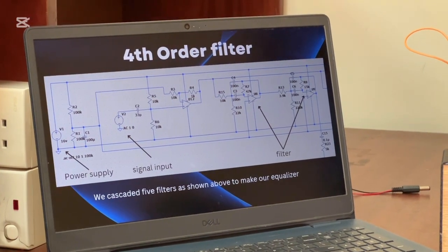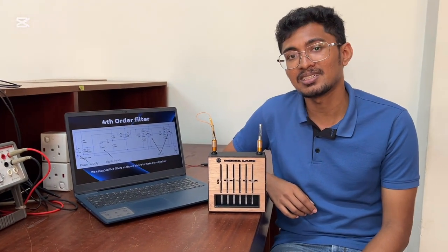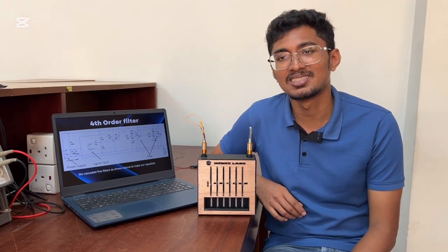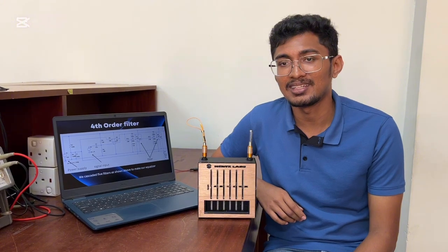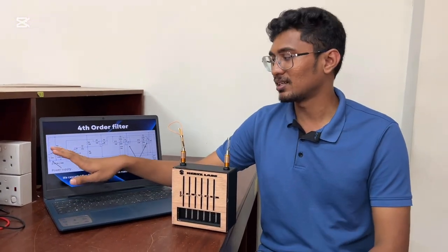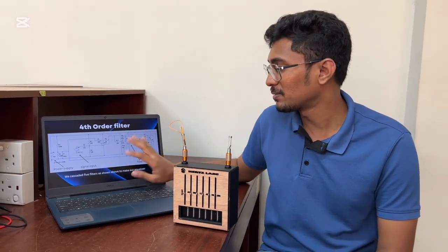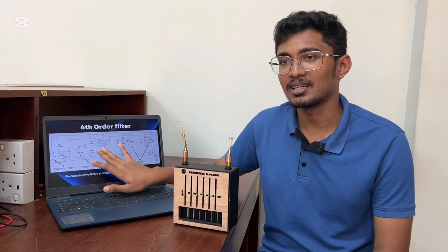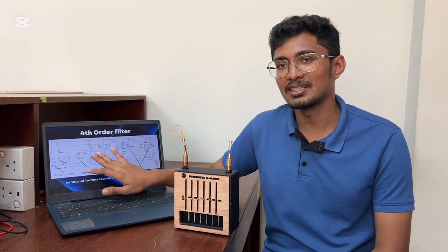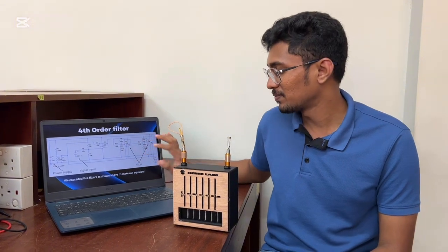We are using an 18 volt single power supply designed to power up our application because dual power supplies are generally not used in day-to-day life. This is the part which supplies the power from the single supply, designed to power up these dual supply op amps. And here we have the input stage, which buffers and converts the signal into a mid voltage, and then the single pass band filter.